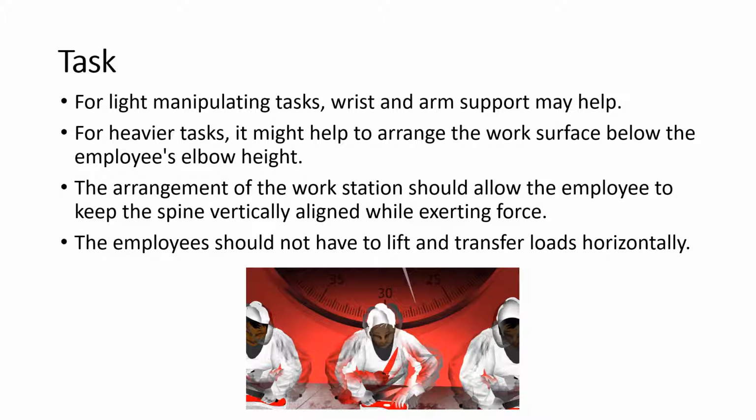And also, it's important that you design the workstation in a way that the workers do not lift or transfer heavy loads horizontally. You know, when they need to transfer the load in the horizontal plane, they need to have spine torsion, or they need to turn to different sides. And as you know, and we talked about it before, spine torsion can predispose the spine to more injuries.